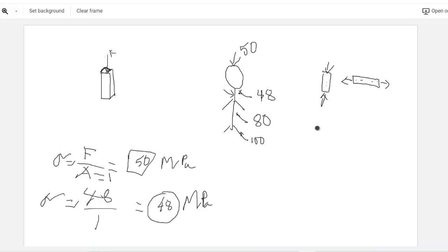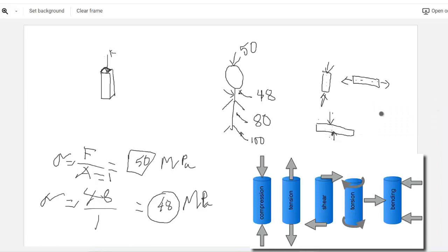Another force you might find is shear force. Shear force is basically the sliding force, which is parallel to the cross section. So if you consider this is the kind of force you are giving and it has a tendency to break here, the resistance force which helps it not to break is the shear force. Do you understand? Which force is passing parallel to the cross section? Please do not misunderstand. Try to understand the key points.